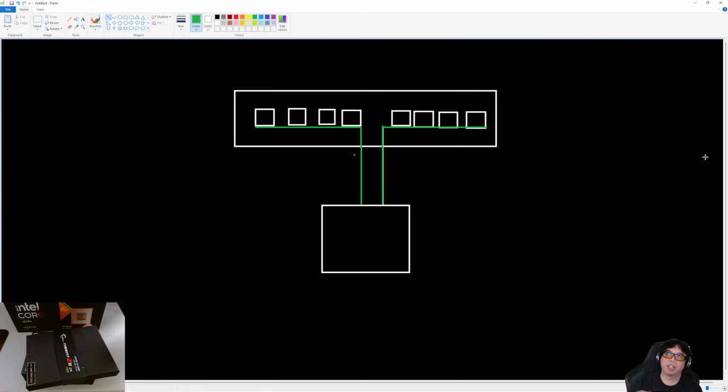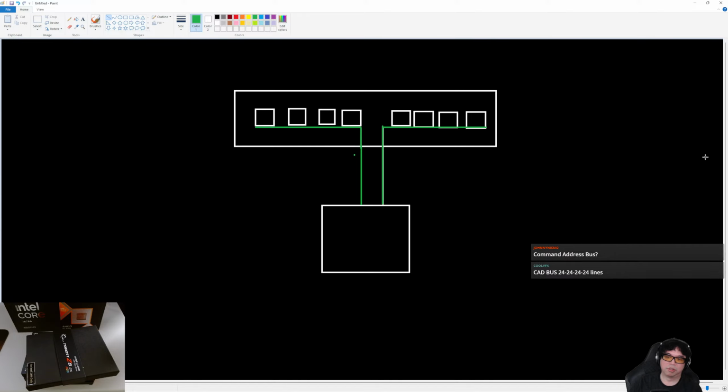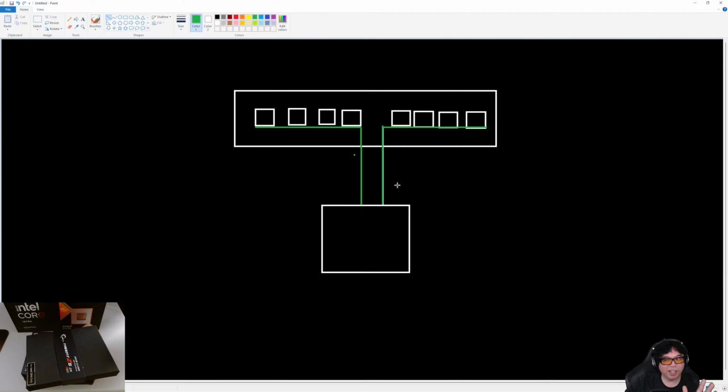This is what I like to refer to as the control of the memory. So this is going to be your clock, your synchronization. It is basically the upper level of the memory control. I don't want to turn this into a layer 3 versus layer 2 topic, because that would start overlapping with the network world, but you can think of it that way: the administrative layer for the DRAM modules. Not administrator in the sense that it's the user, but the commands from the memory controller are issued to the DRAM chips over this interface.